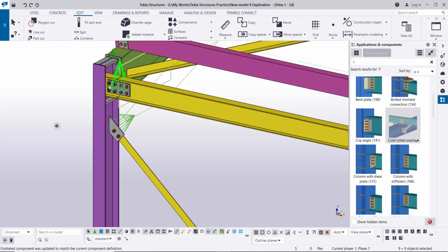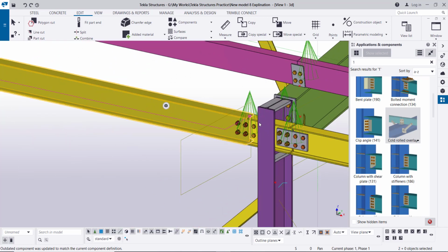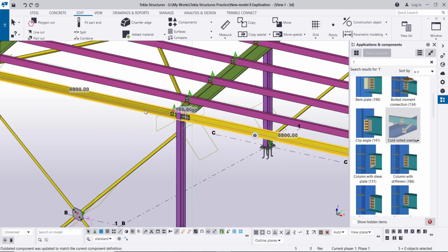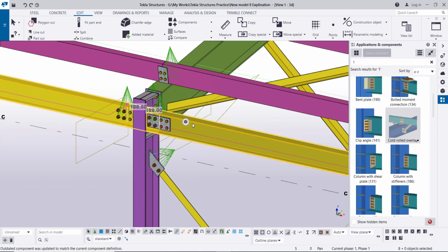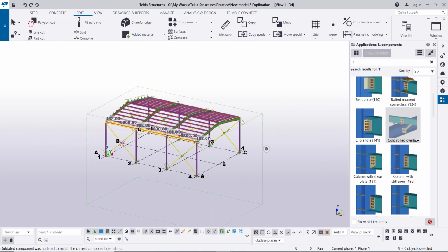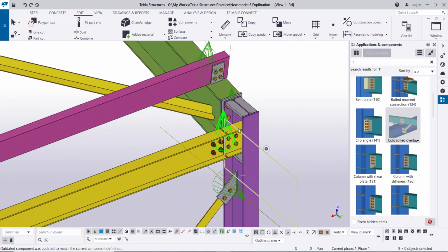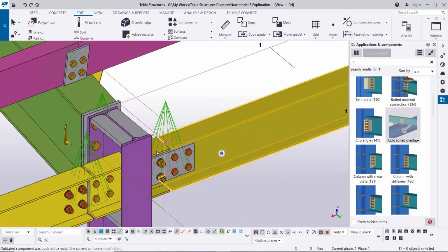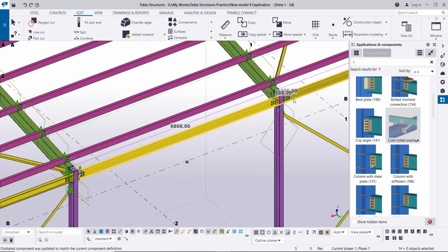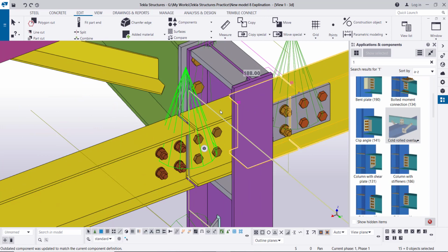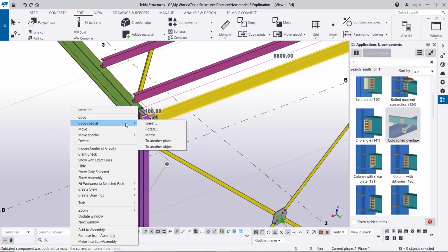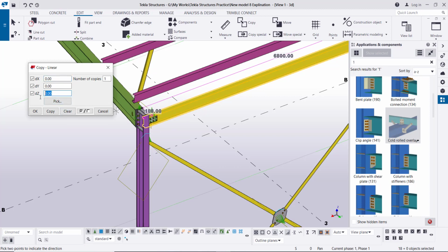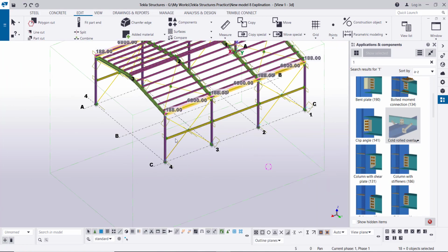So now we can copy these beams, select, we can copy it to the mid-level, the other direction, select both, and then we say copy special linear, click in the Z direction minus 3600, press the mid height, copy, okay, so as you see it is like this.